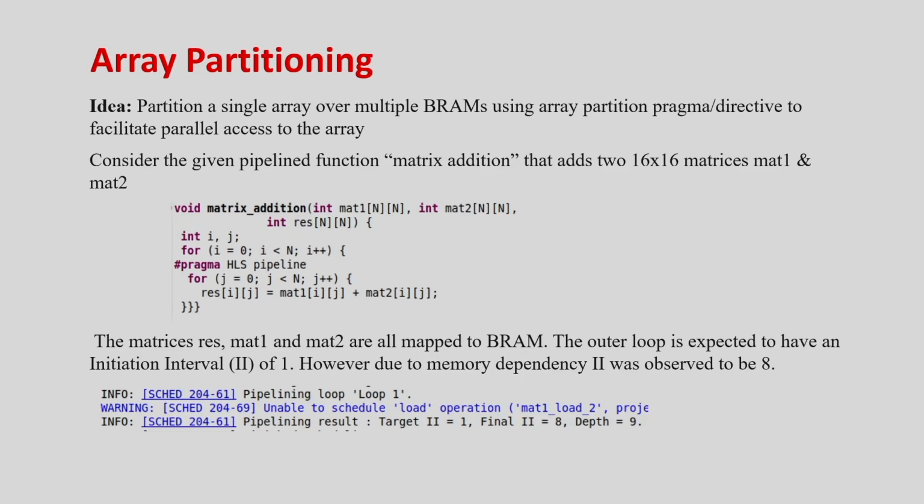The next most important optimization is array partitioning, and it is kind of inevitable, you have to use it, because of the problem of the block RAM. The block RAM has 1 or 2 ports, so you can have only 1 or 2 accesses to a memory, right. And when you have an array, if you have more than 2 accesses, it creates a bottleneck in the loop